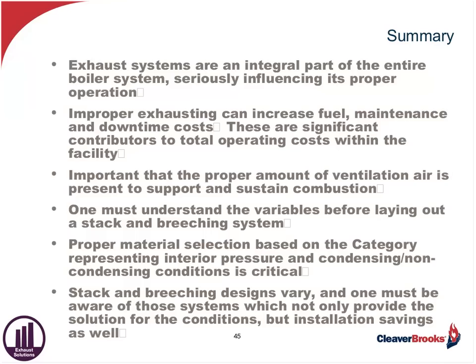And if that means that we've got to go to an induced draft fan, or do something to enlarge the breeching, or do something with the resistance in terms of avoiding the T's and going into Y-type connections, whatever we can do in the most economical way to give that boiler what it needs in terms of draft is what we have to do.